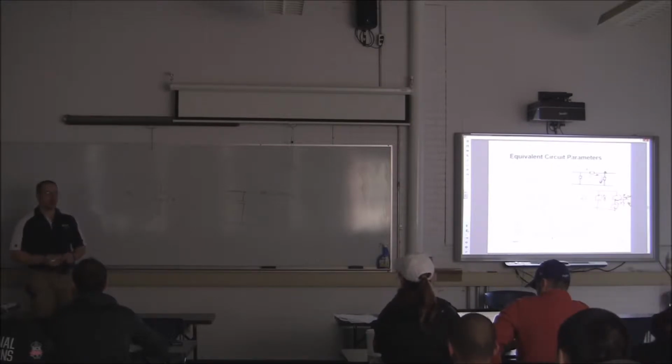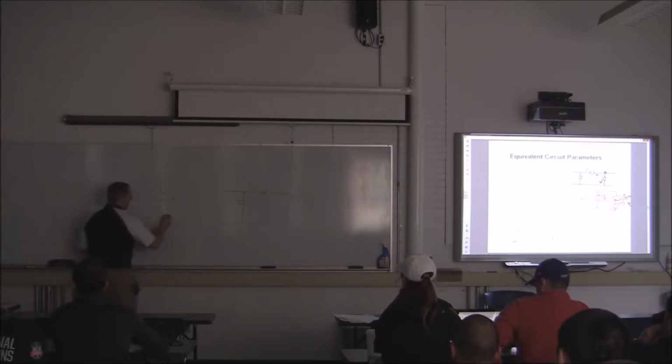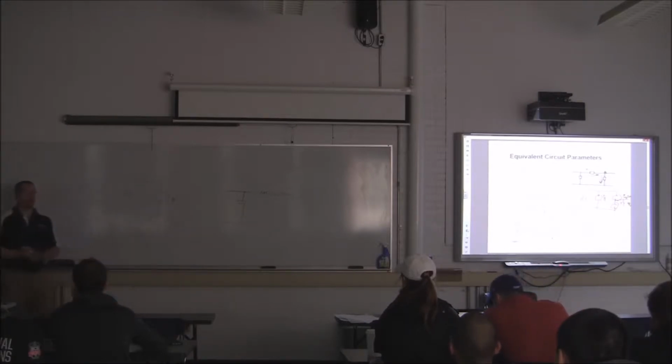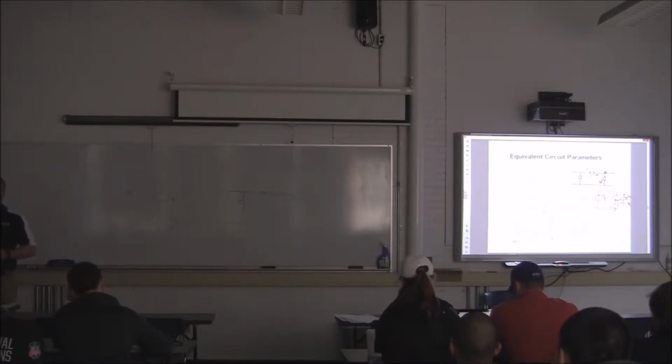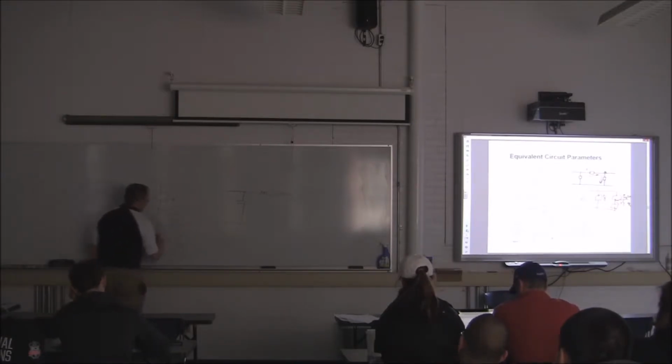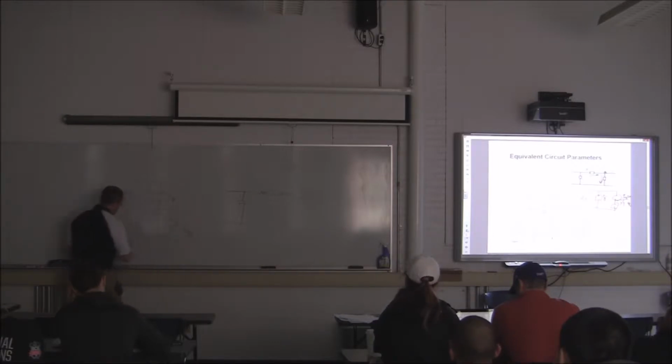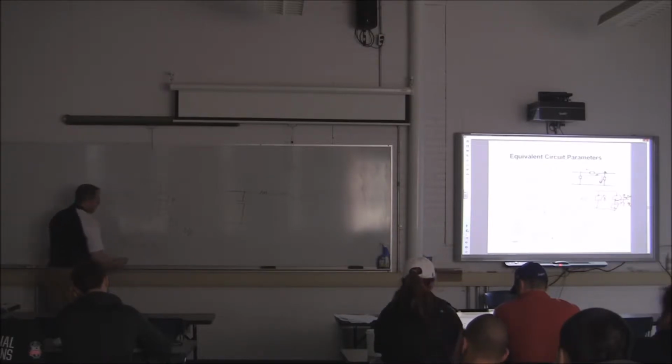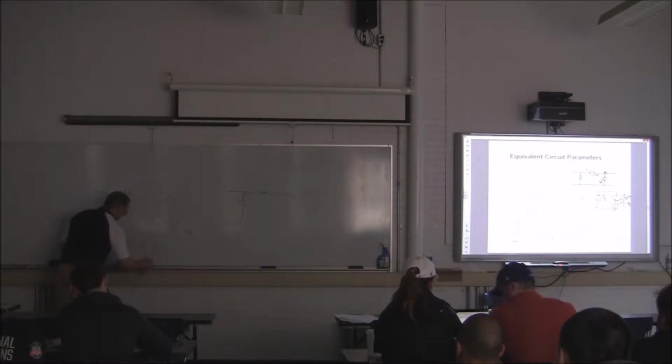For voltage divider, all the units have to be in ohms, right? So this is 2 over Y prime. I have to invert it because I can't use generic voltage divider with mixing of my terms, right? And this here is VR. So VR is going to be equal to Vs times 2 over Y prime all over Z prime plus 2 over Y prime.